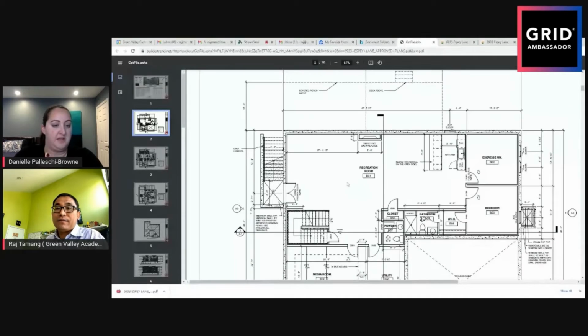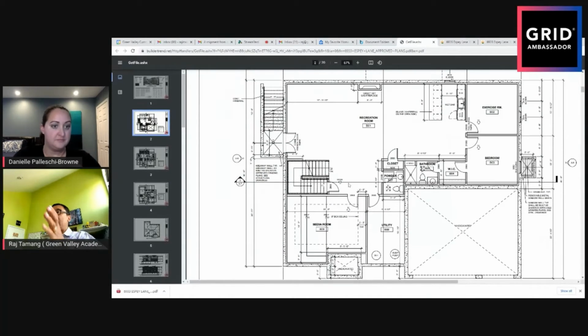Figure out if the load of the house is being carried correctly. Correct. Yeah. So here in the basement plan, you just see the layout, and you know this is a concrete wall. There's an area where there's a stud wall inside, but you really don't know anything in more detail about what type of concrete wall, thickness, reinforcement, footings. All that information is not here.